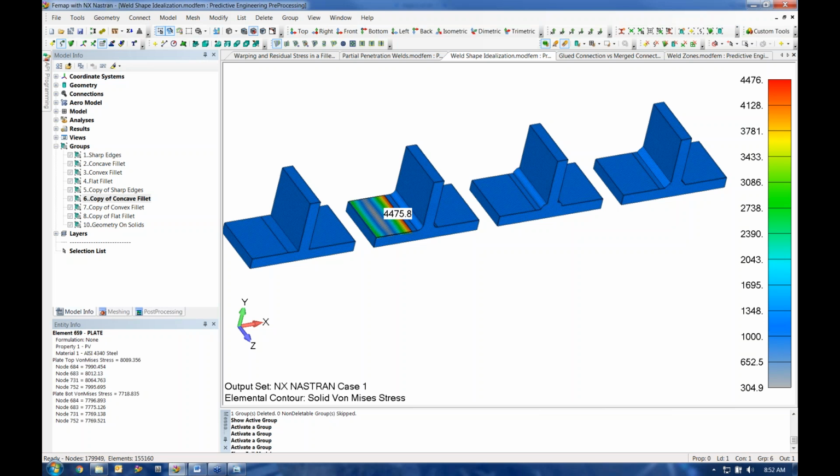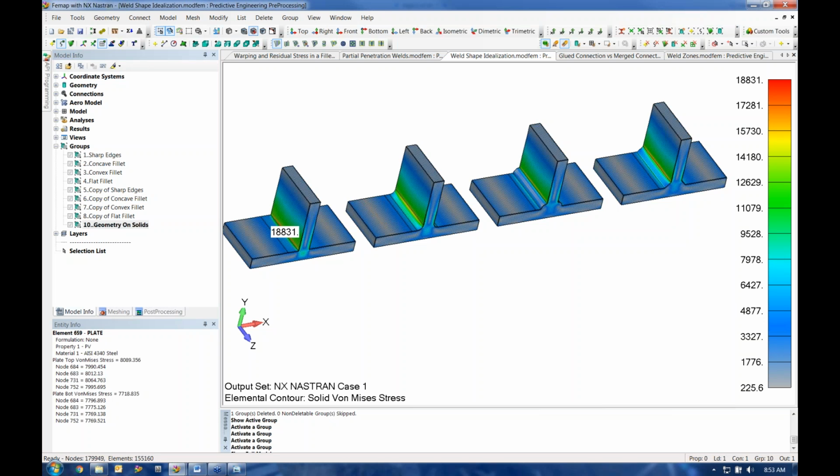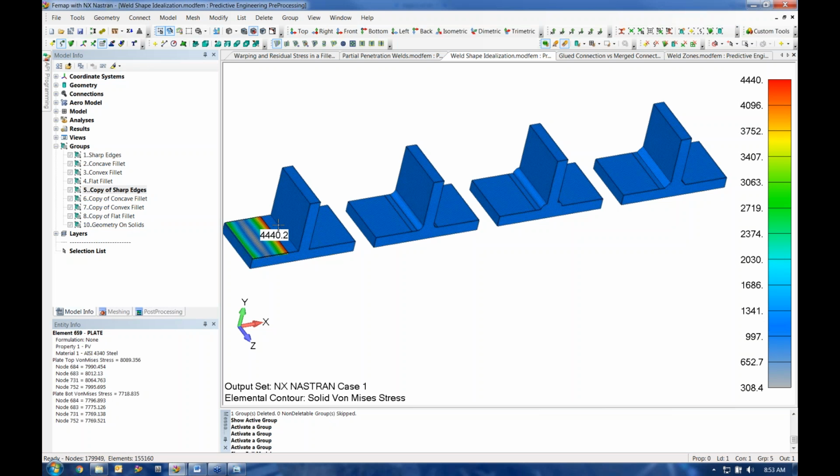Now, I don't really ever like to hide information when I'm describing my models or my results. So when I go through documentation, I'll usually show, here's the full field stresses. You can describe that, oh, this sharp corner is going to be a singularity. Moving away from these singularities, here's our stresses at X distance. A lot of the codes or guidelines that I was looking at, if not using the toe of the weld, it might be one thickness, your plate thickness, away from the singularity.